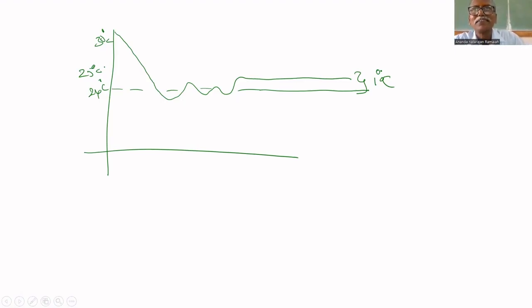Which error? Now error is 0. This additional input is proportional to what? Now the error is 0. Always the additional input depends upon error only, not speed. The difference between set point and PV only. The additional input is proportional to what? Old error. It is proportional to old error.